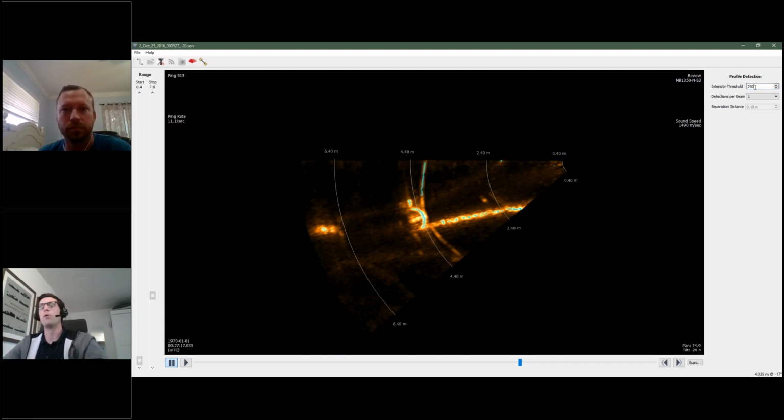And the main point here is all of these settings on the right, I wouldn't really bother with. I would leave them at default during acquisition. I would really just play around with them on playback, because you can play back the file an infinite number of times and generate an infinite number of XYZs with different settings. And it's just much easier in the office rather than on a boat or in outside conditions.